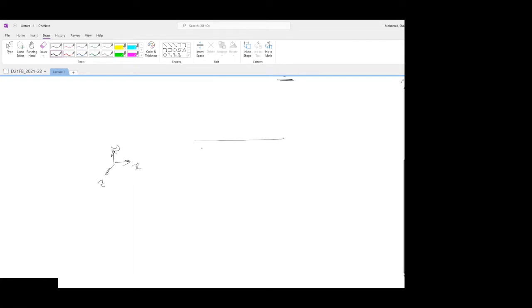So I'm just going to draw a three-dimensional beam. Let us assume that this is the three-dimensional beam we have. All right. Now, this is fixed at this end. Assume that this is completely fixed, this face over there. So this is the back face, and then it is loaded with some uniformly distributed load on this face. Now, again, in this case, the stress is going to be some sort of resultant for this distributed force.